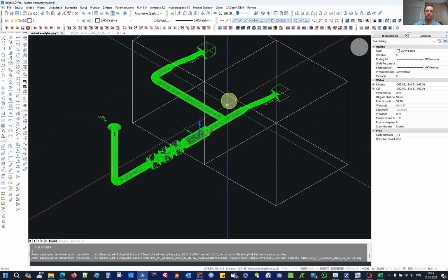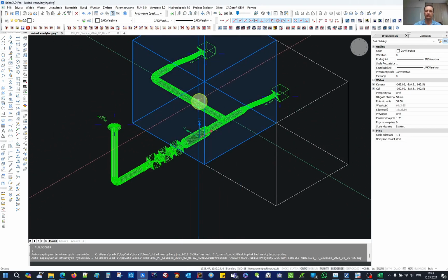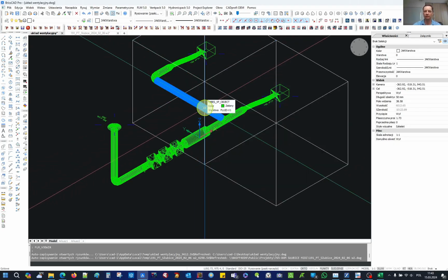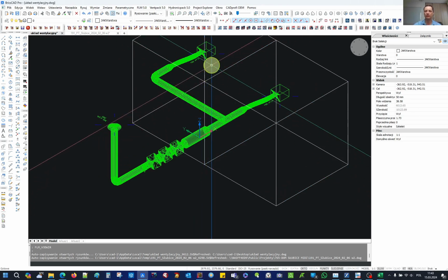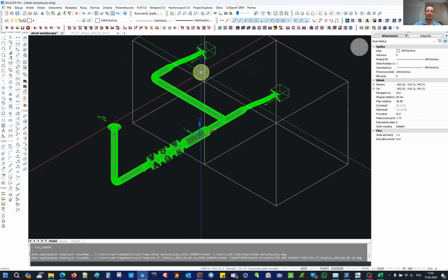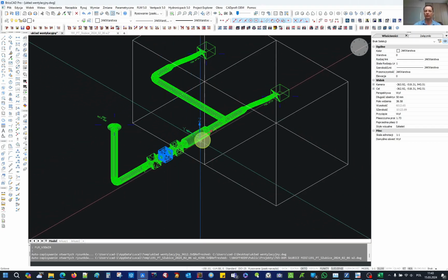We will calculate the noise level generally in this room at a distance of 1 meter from the air vent, and it will be the sound pressure level, which is worth noting, not the sound power level, because our ear perceives sound sensations through just acoustic pressure. However, we define all these elements by providing acoustic power.